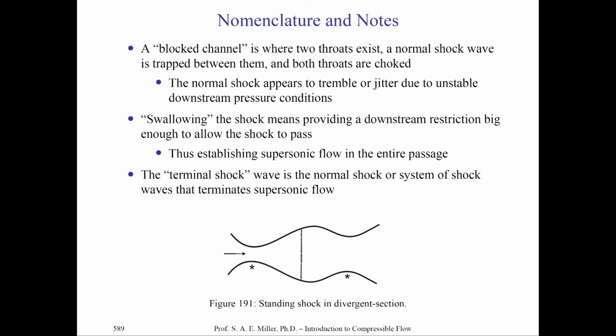The final major concept is, of course, the terminal shock. The terminal shock is the particular shock wave where a shock wave or system of shocks terminates the supersonic flow. For example, in the nozzle problem, if we have a standing normal shock in the nozzle, that would indeed be the terminal shock. So the shock wave that is terminal is always the one which brings the flow back to subsonic speed.